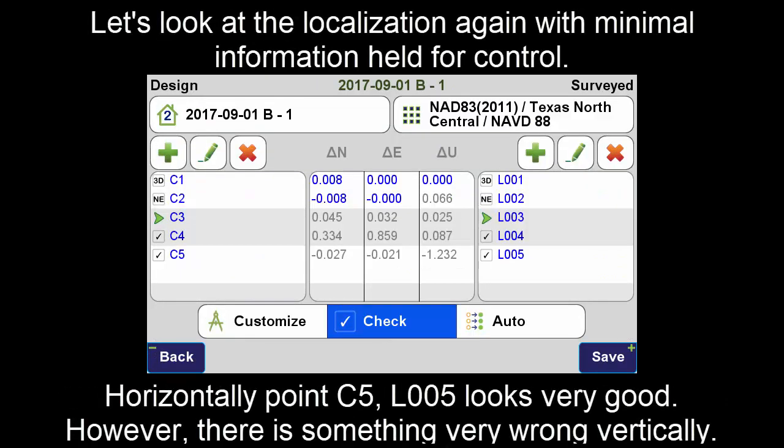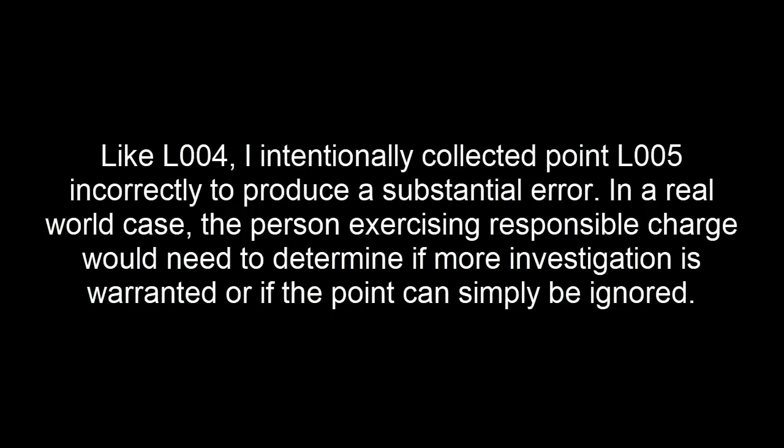Let's look at the localization again with minimal information held for control. Horizontally, point C5L005 looks very good. However, there is something very wrong vertically. Like L004, I intentionally collected point L005 incorrectly to produce a substantial error.